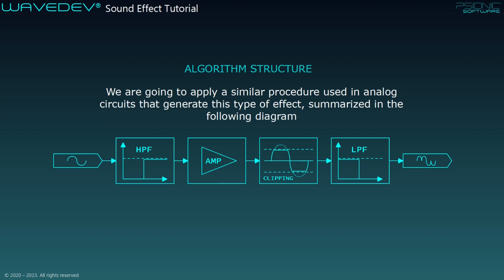Its utility is subject only to the next block, the clipping stage. Both are tightly bound so they can be joined in a single stage called the saturation stage. This is the actual stage that creates new frequency components, therefore distorting the signal. You should know that digital filters can only work on already existing components, but they do not create or destroy anything. So you couldn't build an overdrive or distortion with just filters.